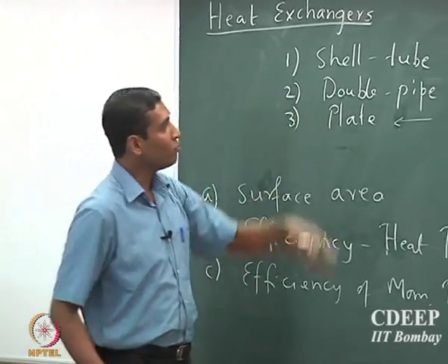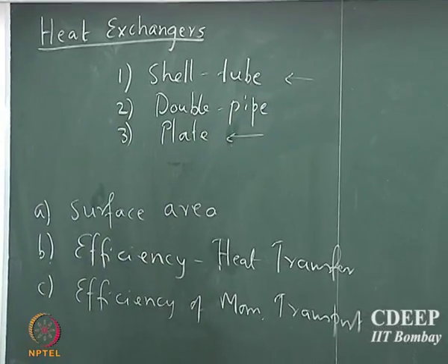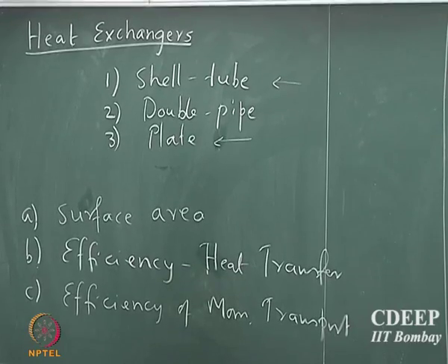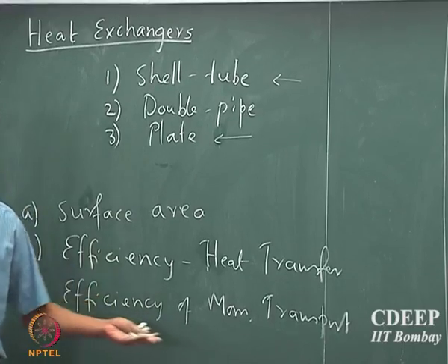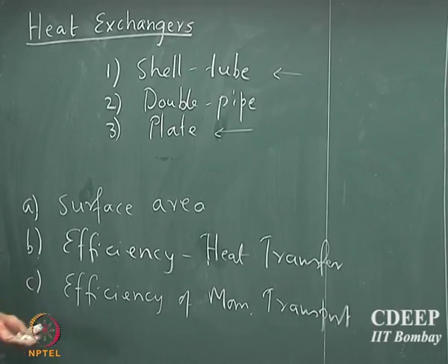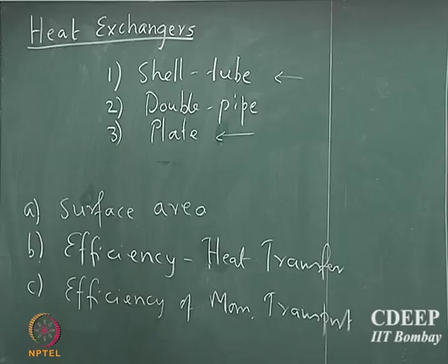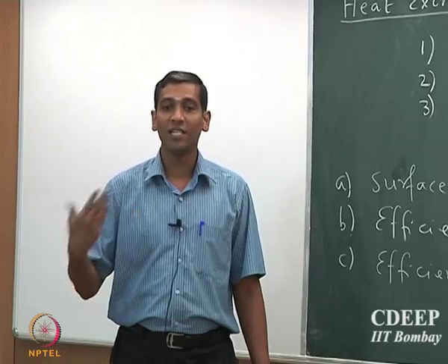And you also do not want to use a small tube diameter. In shell and tube, you have tubes which have a very small diameter, so you will have a very serious issue in transporting those fluids inside the tubes. So, design aspects come into play as to which part of the heat exchanger you flow what kind of fluid.